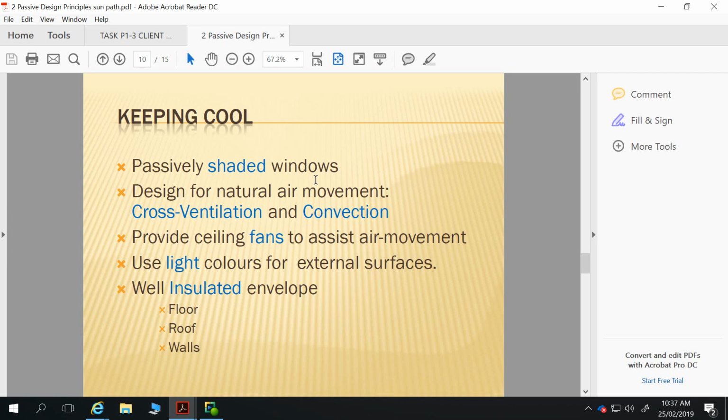And I spent a bit of time in Iran, in the deserts there, where people have been building for at least a couple thousand years prior to the advent of electricity and air conditioning. And some of the designs there for using that convection are fantastic in keeping buildings really cool in a really hot environment, where they've got cooling towers that suck out the warm air from the top of the room, and that gets replaced by vents in the floor that draw air from a cellar space underneath the house. So it's pulling in cool air, and that requires no electricity whatsoever. It's just using that convection.